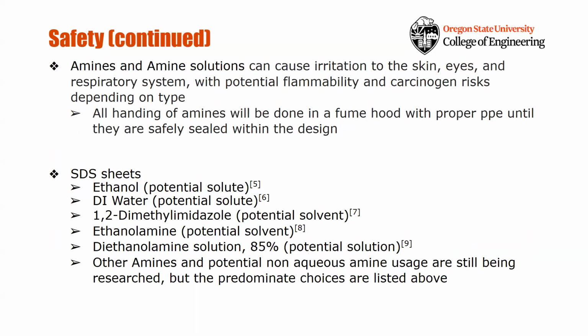Continuing on to safety, amines and amine solutions are known to cause irritation to the skin, eyes, and respiratory system, and some are also potentially flammable and possess carcinogen risks depending on what we're using. All handling of amines will be done within a fume hood, with the proper PPE as stated prior, until they are safely sealed within the design, and even then, especially during early stages, that will most likely still be conducted in the fume hood.